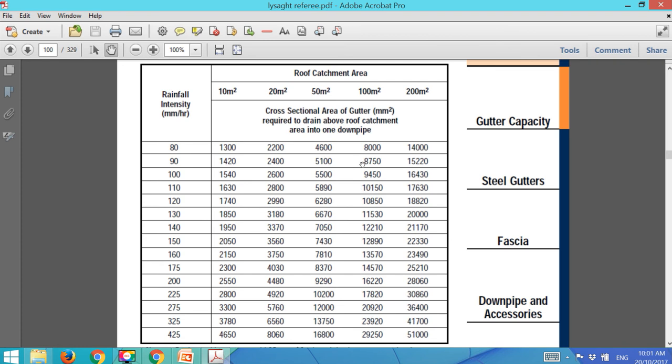So that's, I'm sorry, let me retract that. That's the cross-sectional area of the gutter that you need. So basically, your gutter is going to have to be 167 by 167, which is not very big, right? If you think about your 300 mil long scale rule, it's only slightly more than half of that. So really, we're not talking about large things.